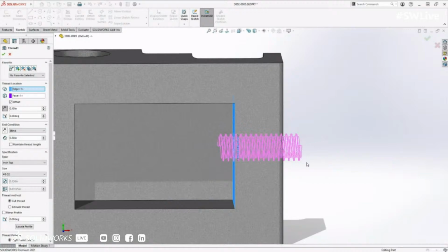You look really dumb standing in front of your customer. So ever since I made that mistake, I run the threads 100 thou through either side. That way I absolutely know there's no way I'm going to have too short of threads and not be able to get stuff to go together.